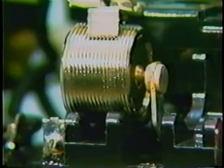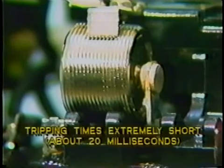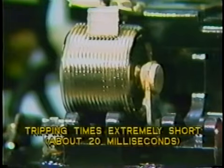The spring restrains movement of the cylinder. However, as soon as the current flowing through the coils increases above the set pickup value, then the induction cylinder will rotate and close its trip contacts. In this unit, only a few millimeters of rotation are required so that the tripping times are extremely short, about 20 milliseconds. Clearly, the directional element plays a very important part in coordination and selectivity of the system protection schemes.